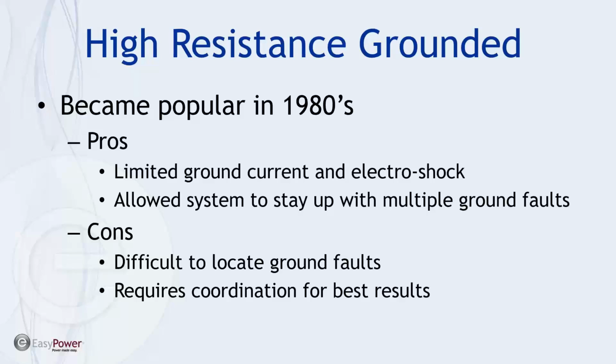Resistance grounding is usually referred to where we have a fixed resistor in the system that limits the current and allows me to monitor the current through that particular leg or ground point. Frequently, that would be the ground on the transformer itself.